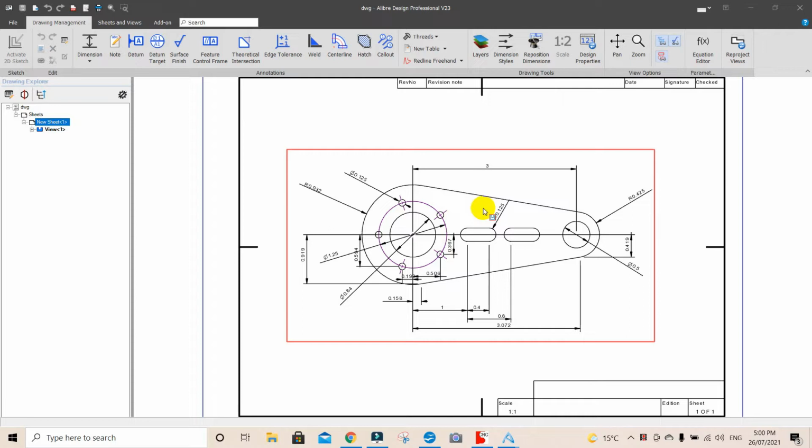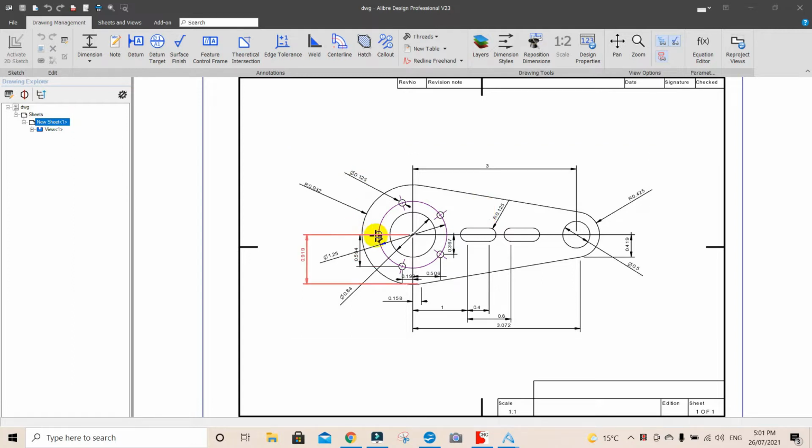My friend's drawing. Let's look at the next leg. We've done all the 5 holes on a PCD around here. We want to look at these holes here. They're 0.84 diameter and a half inch, 0.5 inch hole here, of course, for an imperial. We want to do those 2 holes there, and we want to use a particular feature that I'll point out.